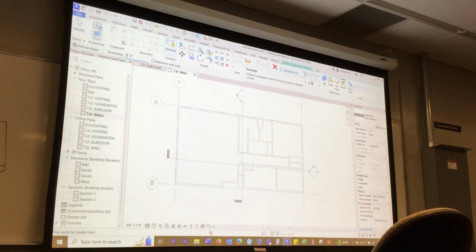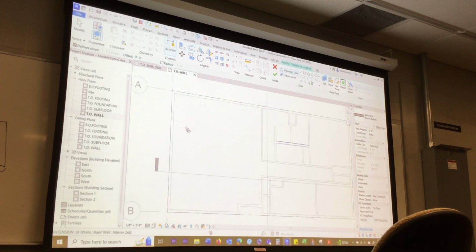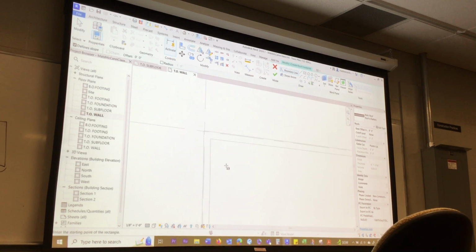I'm kinda winging it. I'm gonna use the rectangle tool. And where would the trusses land, do you think? Like the truss heel or rafter heel? In plane with the sheathing. Like you can take a heel face on a truss and it should line up with the sheathing and it should line up with the engineered floor system and the foundation, the whole ball of wax. On this style of house, like there's lots of variations to this, right? But this is just a plain Jane. Okay, so I'm gonna grab it right there at sheathing.